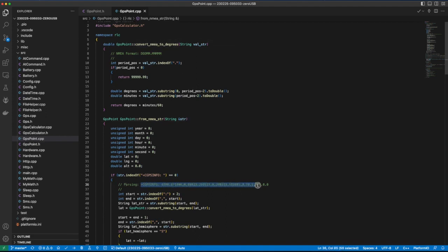This is the format of the string that we're actually getting. And you can see, here at the very front of this, there starts to be some comma separated data. And you can see all the different parts. So this part here, this is the latitude, and then it's either north or south. And then the next part is the longitude, and you'll see either east or west here. So this next bit is the part of the timestamp. It's date, month, year, followed up by the actual hour, minutes, and seconds. And then there's a parameter here for altitude. So that's really what we're parsing in here.